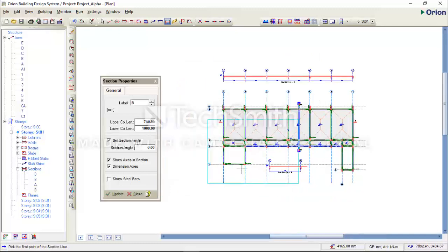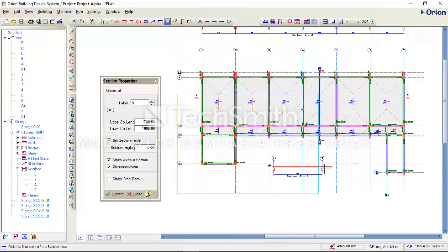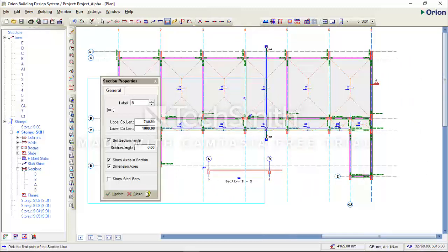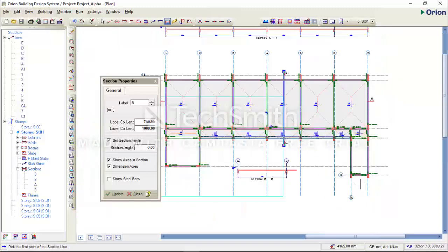In our next tutorial, I'm going to apply staircase load on our staircase beam. For example, this half-turn staircase, I'm going to apply our staircase load. Orion 18 cannot model the slab element of a staircase. So what we can do is just model the load that is being transmitted from the staircase to the beam, to the structure. I'm going to show you how to compute staircase load manually and how to input that staircase load value on your beam on Orion 18 software in our next tutorial.